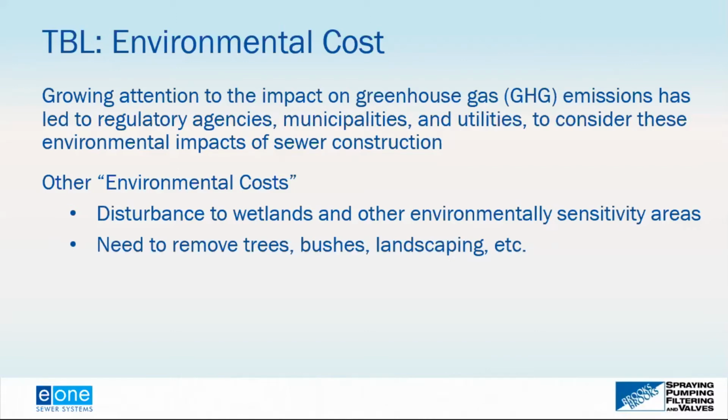Also, it can be installed with either horizontal directional drilling methods or low impact cut and cover, where you have a much smaller backhoe, or depending on where you are and your frost line is, maybe just a trencher to install the pressure sewer system as compared to the gravity sewer system that would disturb a lot more.